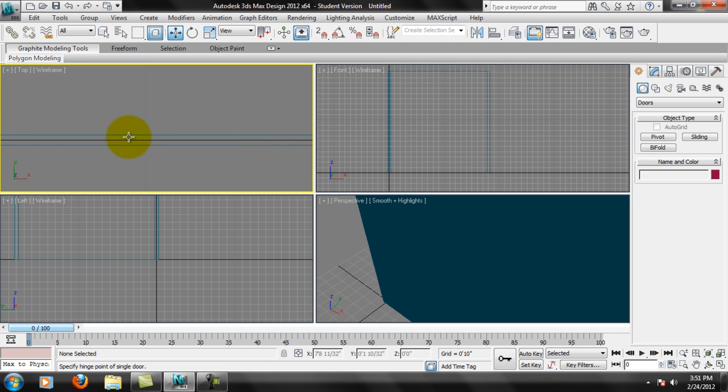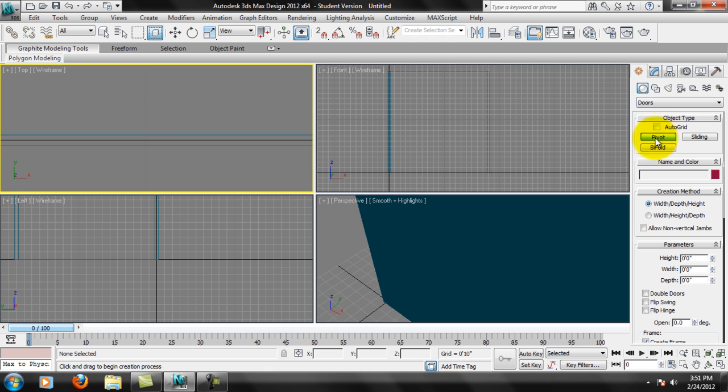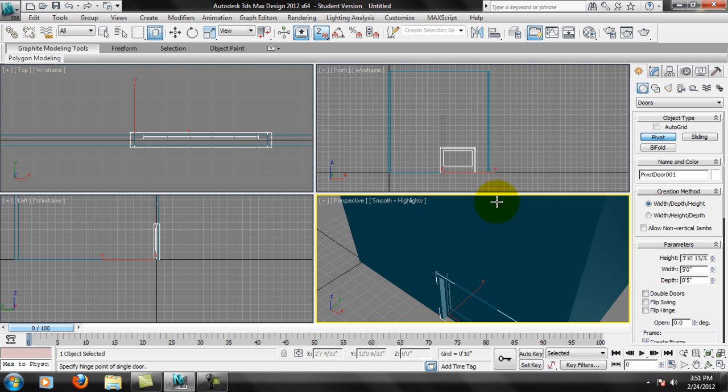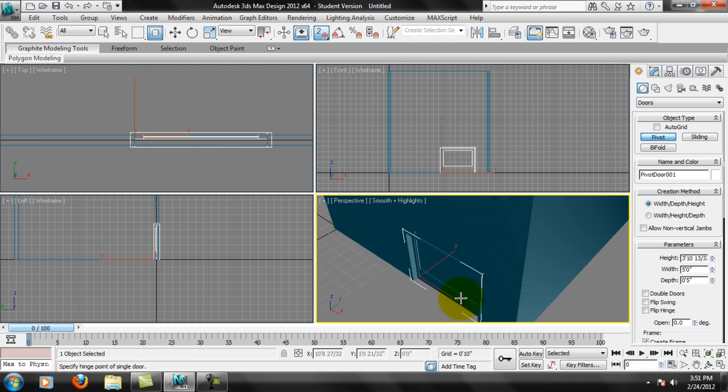If you get that error, usually what happens if you try and place a door with the snaps and you follow every step the way you're supposed to and it still doesn't work, usually the wall's flipped inside out, so instead of starting on the inside of the wall, start on the outside of the wall. So let me try that again on the outside of the wall and turn on my edge snap and try this process again. And this time go to the inside. Okay, there, definitely cut through there.